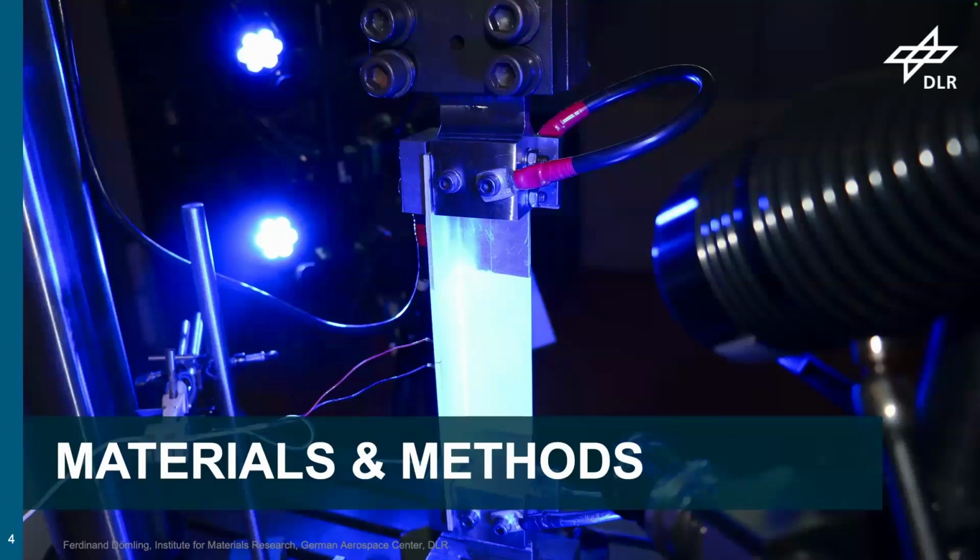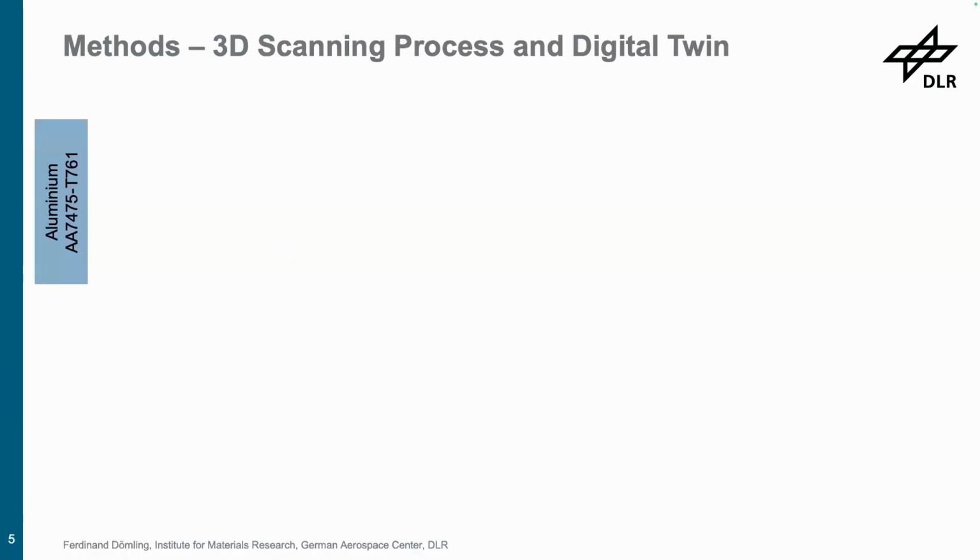Okay, so how could we tackle the problem? Well, we test these angle sheet components for fatigue crack growth. And how can we do that? We start with our material. This is in our case AA7475-T761. This is a high-strength aluminum alloy, roughly about 71 gigapascal of Young's modulus, 420 megapascal of yield strength.